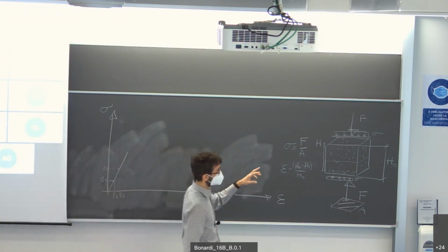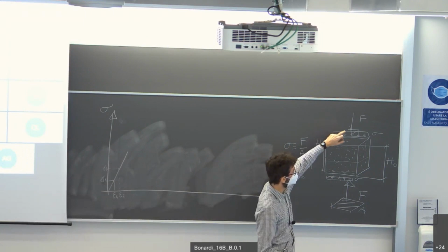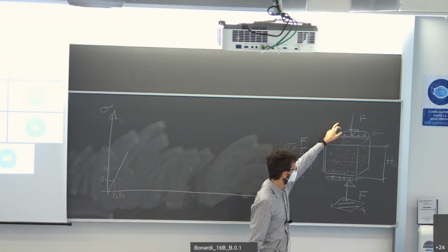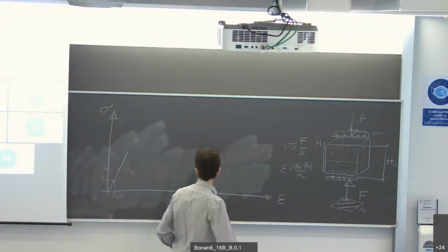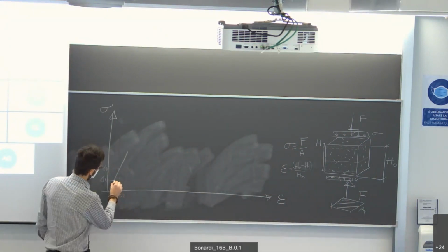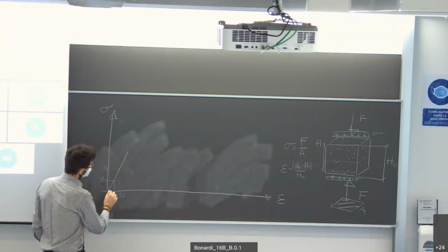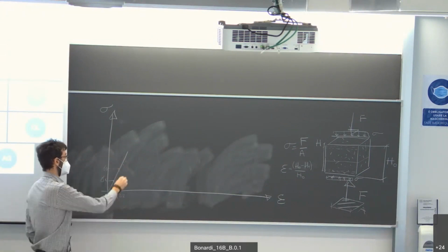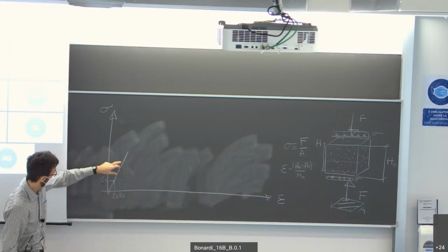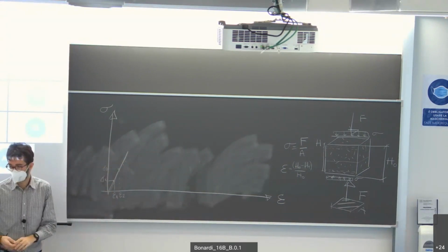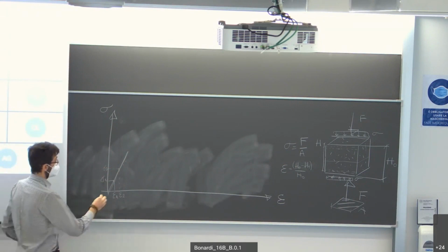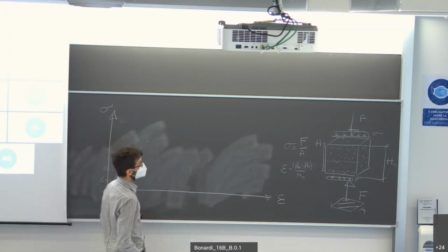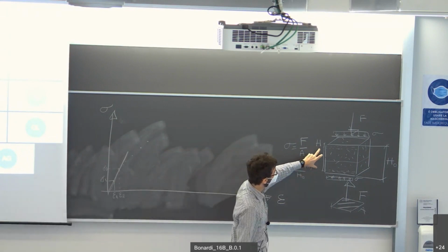Actually, for the concrete, if we increase linearly the stress, or the load, the strain will not increase perfectly linearly, but will tend to be always a little bit more than what it should be in the linear case. So this linear assumption holds only for low levels of stress, not the real behavior of the part. It is as if it is deforming more than what it should.